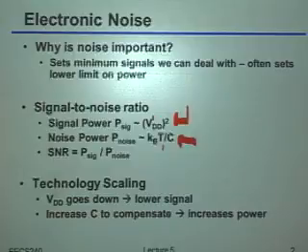In fact, I think I'll have this example a little bit later on, but I would encourage you to calculate, in the analog domain, if you wanted to get 32 bits of resolution from an analog amplifier, which, by the way, I don't think anybody has ever really done, but let's just pretend, how big of a capacitor you would need, given that your power supply voltage is only 1 volt. You'll see that the number you get will be something astronomical, which is why, obviously, no one has ever actually done it.